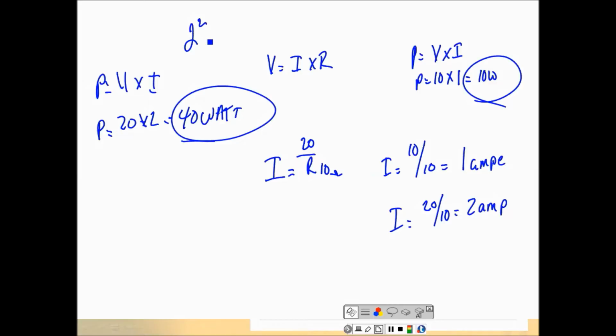So if I've got a relay that's designed to run off 120 volts, and it's got to have a certain amount of watts to work, and I drop that down to 60 volts, that relay is not going to pull in anymore. It's not going to have enough energy to pull in because I halved the voltage. If it goes down, it's 1 over the square. If it goes up, it's times the square. Because if you halve the voltage, you halve the current. If you double the voltage, you double the current. So power varies with the square of the voltage.